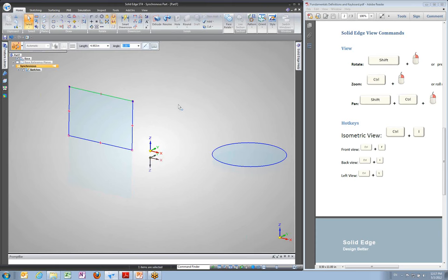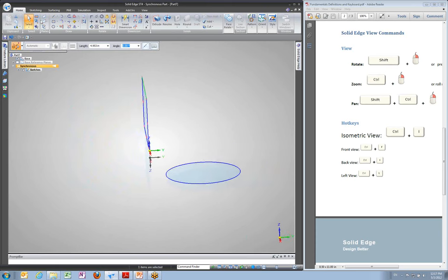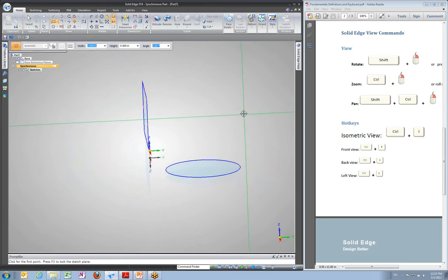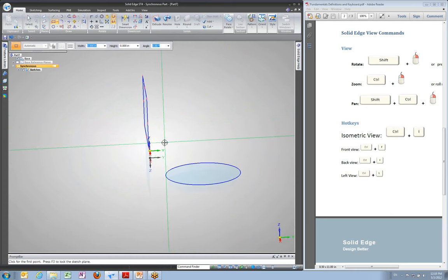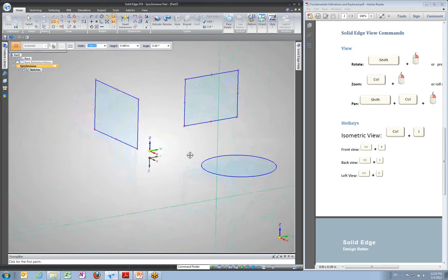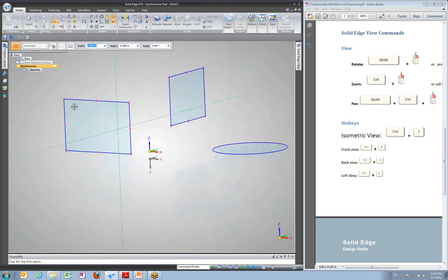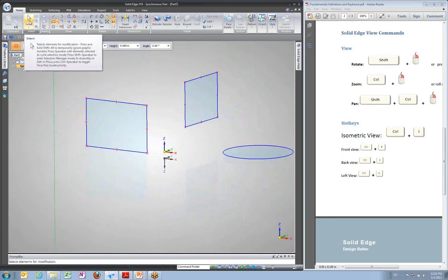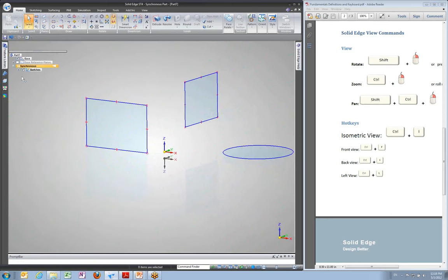All right, let's rotate my view once more to this side and pick another rectangle, let's say. And I'll place a rectangle. Now you can see that I'm mostly oriented towards the ZY plane. So when I click and draw that piece of geometry, it's on the ZY plane. So I've got three different planes, three different sketches. And in fact, if we go back up to my select tool and reach up here into our property tree and expand Sketches, you can see that we have three different sketches. And by mousing over them, each one will highlight.